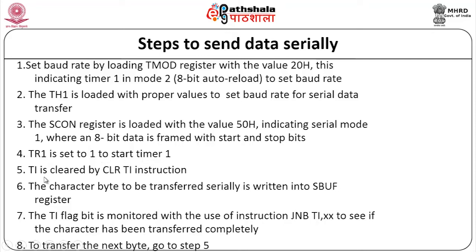Then TI should first be cleared, because if it has accidentally been set, it has to be cleared first. Then the character byte to be transferred serially is written to the SBUF register. Whatever data we want to send serially has to be written to SBUF. After that we have to wait for the TI flag to be set by the system. That means the serial communication is sending outside.